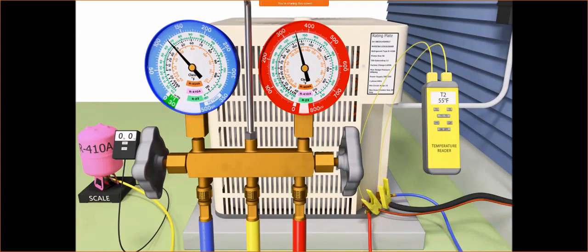Before adding any refrigerant, make sure that you are purging the air out of the hoses before connecting to the refrigerant bottle. And remember that if you're really low in refrigerant, then you really wouldn't want to add refrigerant into that system. You really want to find the leak first, because what's going to happen is that refrigerant will just leak right back out again, and that's no good for the environment, and it's not good for the customer because they're going to get upset again.